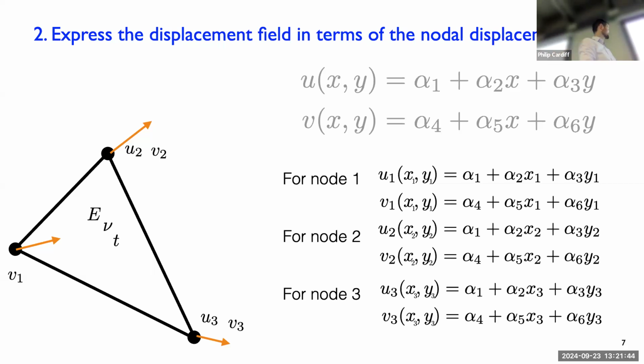How can you fit a quadratic curve with just 3 nodes? Well, in that case, if you select that, Abaqus actually adds extra nodes at the mid sides or in the center of the element. There are a few different ways to do it. You may just put them on the outside, you may put some on the inside. There are various ways to do that. And that's where Abaqus stops. You can't go to cubic, but other finite element software out there might have cubic or fourth order, etc.